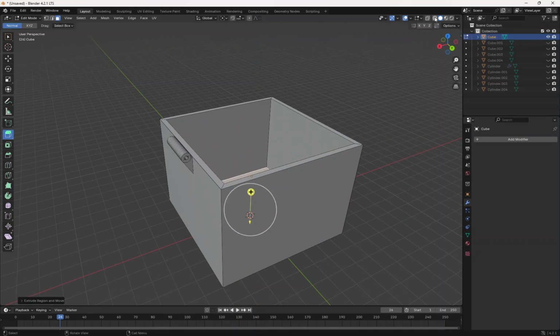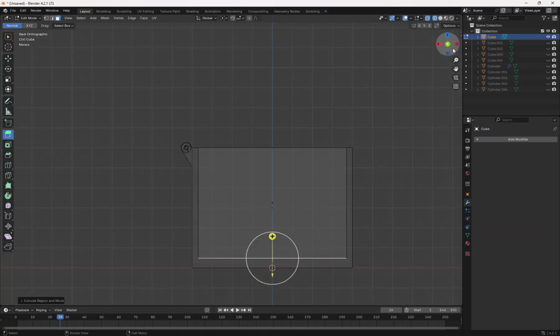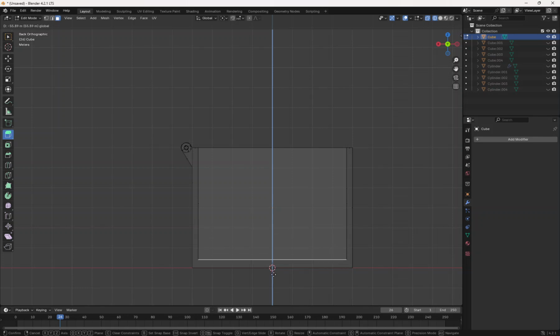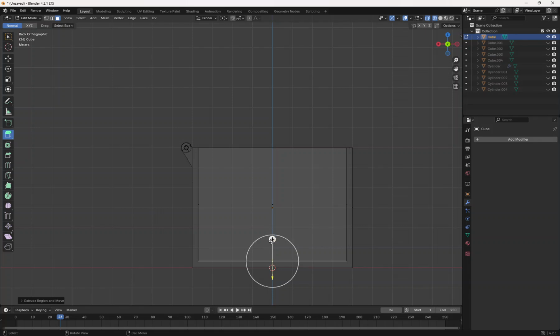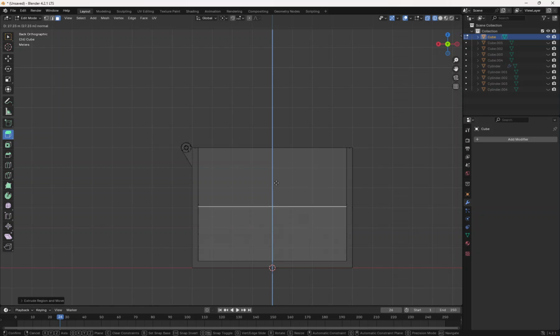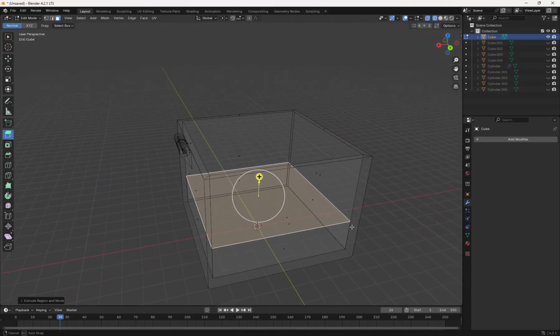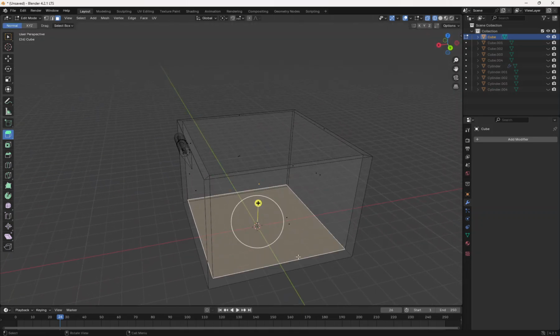If we go to then wireframe mode and one of our Y or X axes, you can see here that we can continue to drag this so that it looks kind of parallel with the rest of the box that we just pushed in. Be careful doing that you don't hit the plus again. That's going to do a separate extrude, and that's not what we want. We wanted to move that face itself.